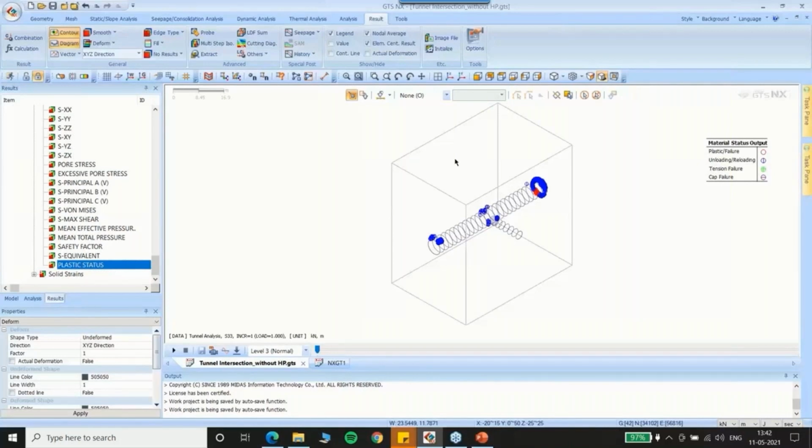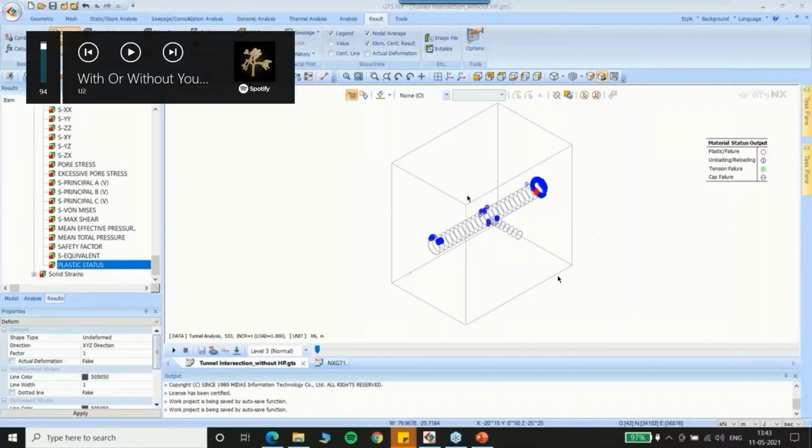Here, what you can do is always reduce the thickness of your shell element and then check what kind of deformations you are getting. As long as the model is not diverging and your deformations are in the proper range, you can always use the same model as a benchmark to test what other criteria you want to fulfill in there.